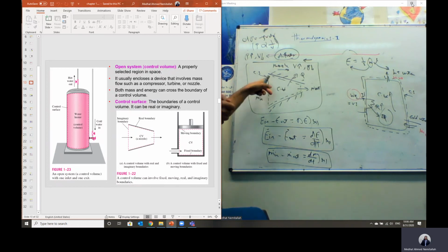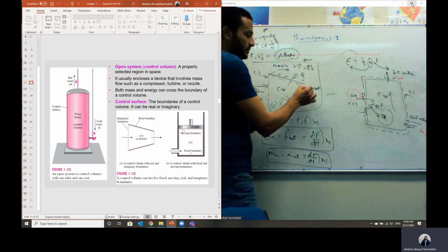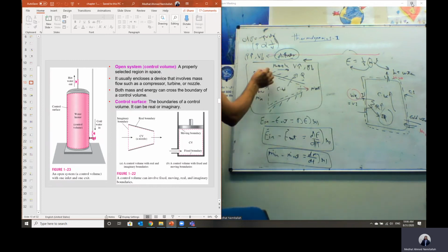In the hydraulic turbine, the nozzle is used. We have water, usually with a kind of dam, and we have a high level of water in front of this dam. So at the base, the pressure should be very high. Then we have high pressure flow through this nozzle, so we have high flow energy in terms of high pressure.